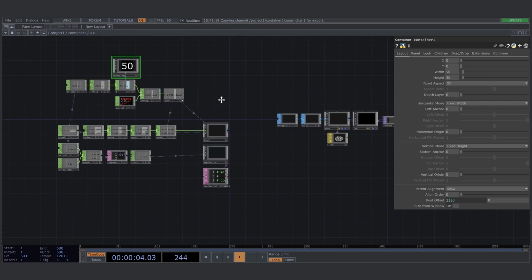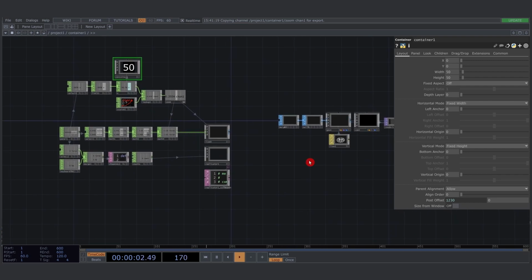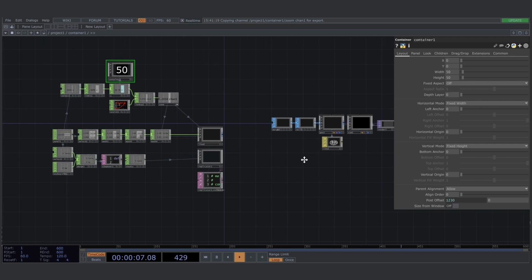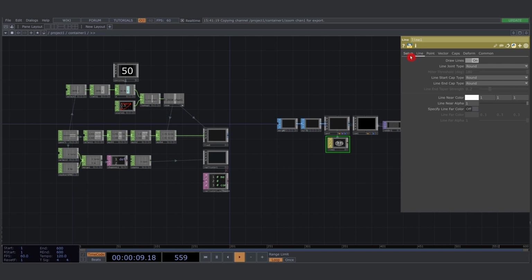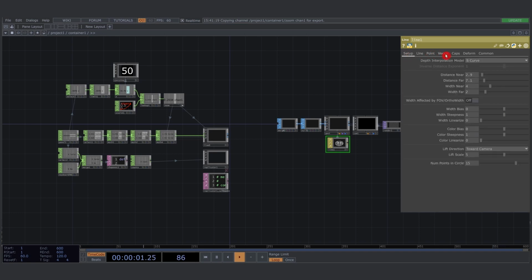Let's see what's next. Next, we can still make the line width a bit more responsive. Most of the time I just put this at 0, since we're just working with an orthographic camera. There's no real depth or perspective to use this far near stuff, and I'll just put these ones at the same level.